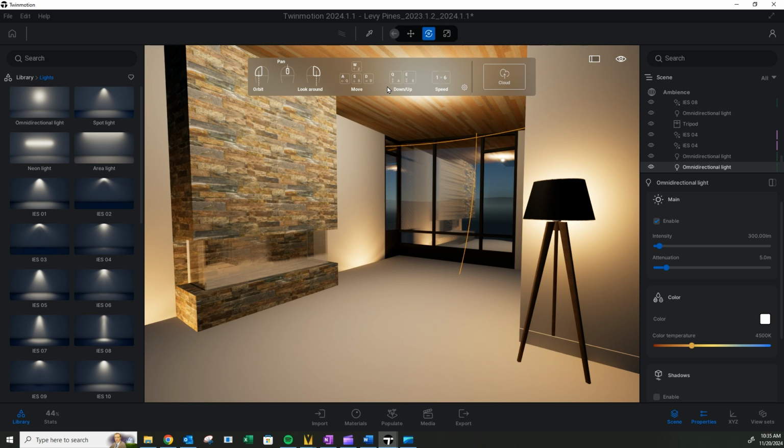So if you have a light in your ceiling without optics and it's only a short ceiling, just flooding the space might work. But if you get a 20-foot ceiling, those lights without the optics to focus that cone down that we were talking about earlier are not getting functional light to the work plane. It actually loses 90% of its light output by the first 3 to 4 feet. So it's not really doing any good.